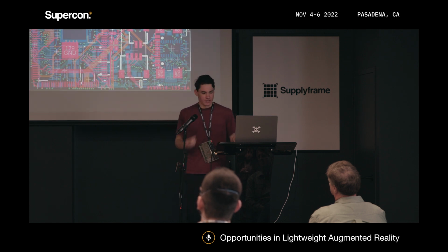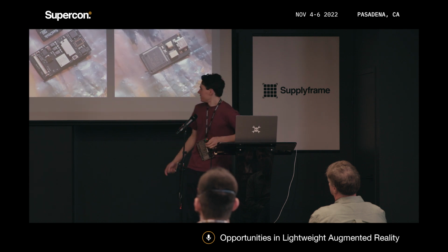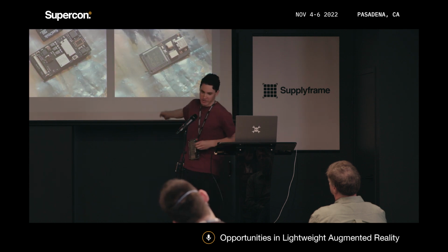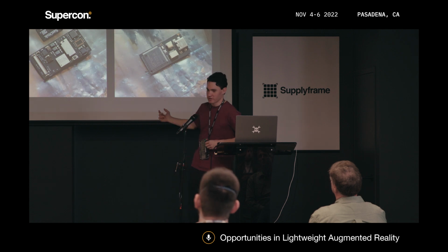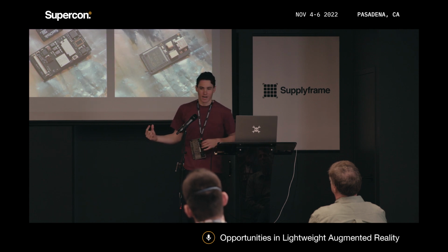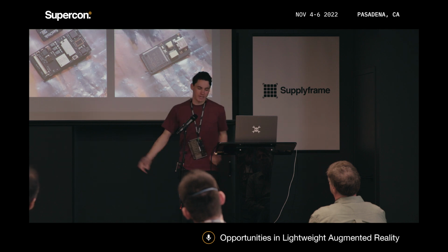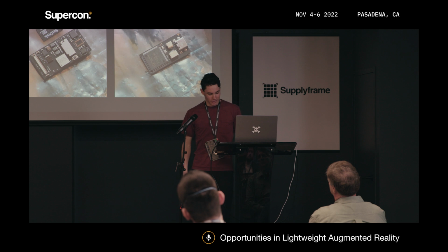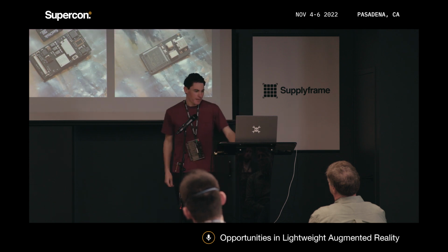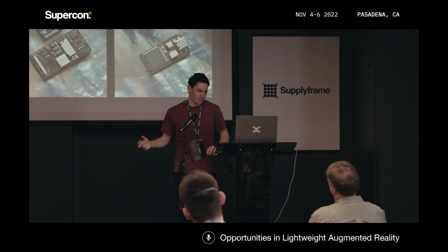So this is another iteration of my design. Now here I've switched to a different system on chip. As you can see in the assembled view, this is using this package. It's marked F133. It's also called the Allwinner D1, which is known as one of these new RISC-V system on chips. This is made on a 22 nanometer planar process, so it's relatively efficient in comparison to the older 40 nanometer STM32MP1. So this chip also has a dual link LVDS interface built in. So you don't need any sort of display interface bridging.